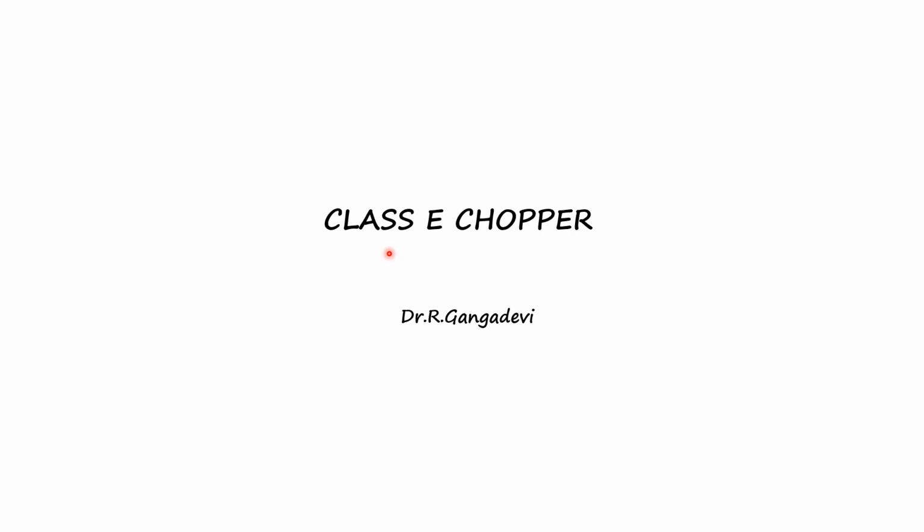Hi everyone, in this lecture we will see the operation of class A chopper. It is a 4-quadrant chopper. The power can either flow from source to the load or load to the source. In the first quadrant, the class A chopper acts as a step down chopper, whereas in the second quadrant it behaves as a step up chopper.